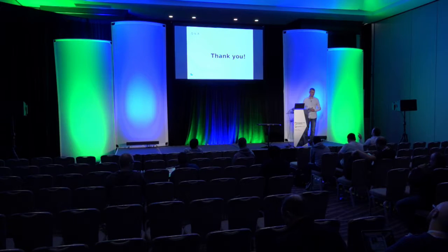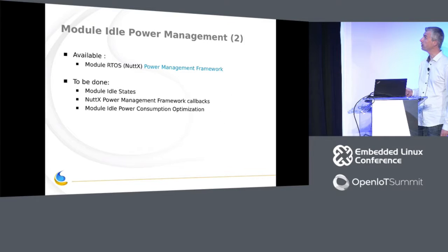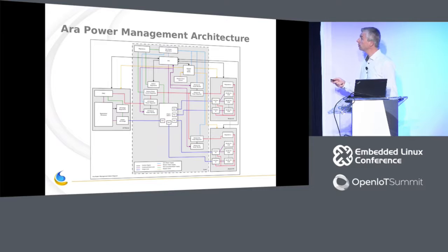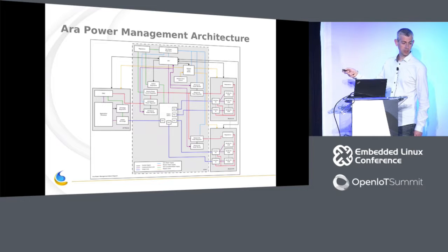Can you elaborate how the Greybus protocol and runtime PM interact? Yes. Okay, so the question is about how Greybus and runtime PM interact. So I'm going to go back to the slide of the power management architecture. So we are on the application processor, okay? That's where Greybus is, and that's where all the drivers are loaded and instantiated. So they implement the runtime PM calls. So anytime a runtime PM callback is invoked, that will be turned into a Greybus operation,